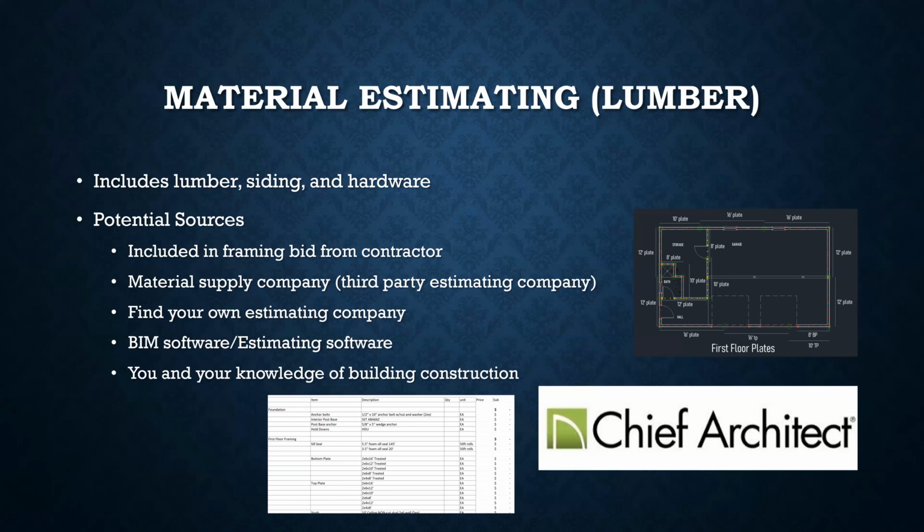And then of course you can always do the material estimating yourself. If you have enough understanding of how things are put together, you can understand that, okay, I'm going to take my sheeting goods and stand them up against the wall and go around the house. And so whatever my linear foot around the house divided by 4 feet is, then that's about how many sheets I need. So you can also do your own materials estimate. And that's kind of where I started. I picked up my own list and things like that.